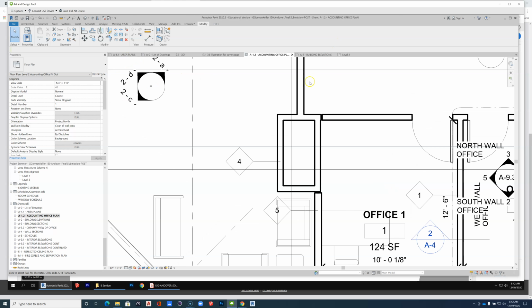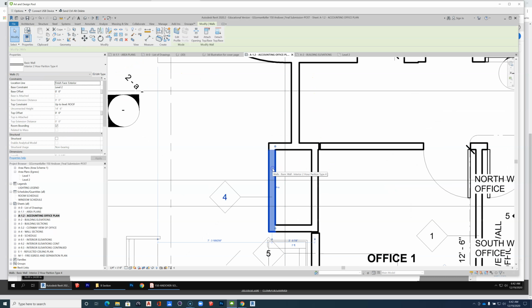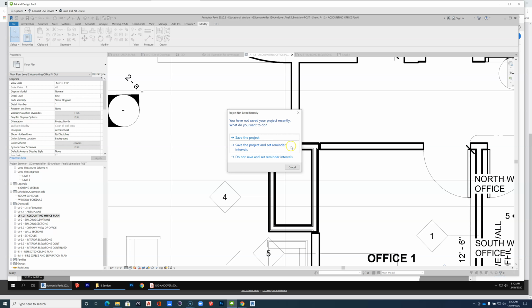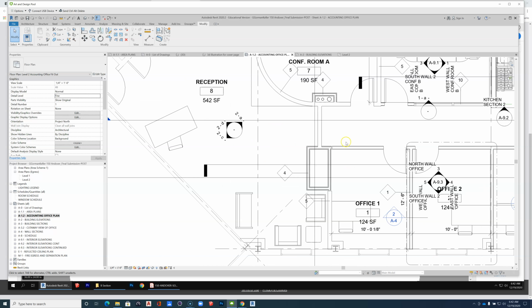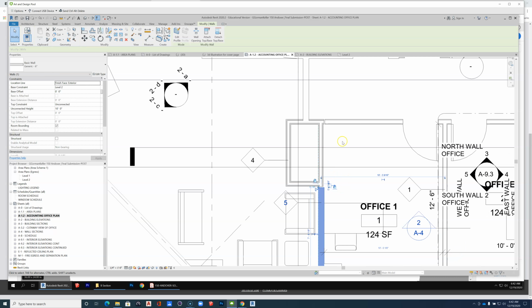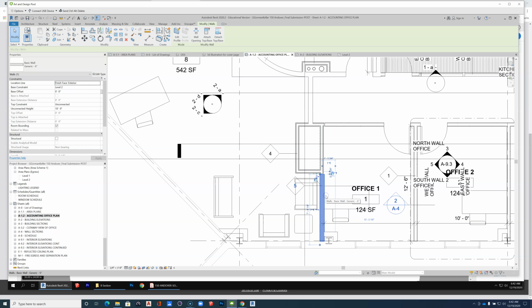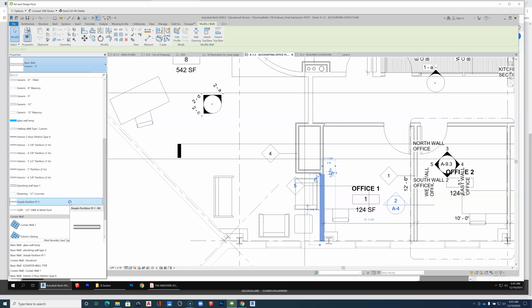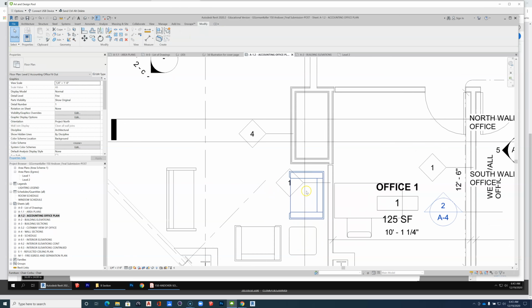We could create one. We can't see the layers in these walls, and I know that we made a 2-hour type, so I want to change the detail level from coarse to fine. All right, and then TL toggles off and on the thin line mode, right? So that wall is still a generic 6. That is a simple partition type 1, that's right. This wants to be a simple partition type 1 as well. So find that. Once you use it once, it's right?